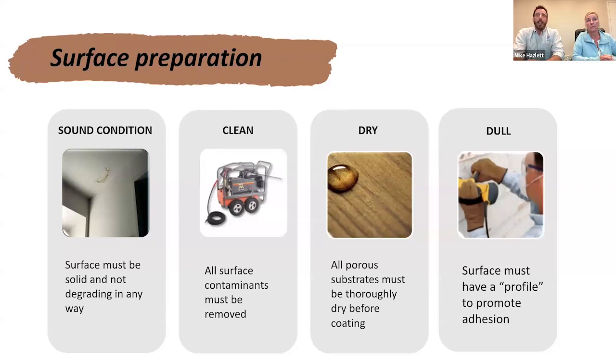Come back in two hours, maybe after lunch, and more than likely you'll have condensation underneath that bag. That shows that even though it visibly looks dry, there could still be moisture coming out of that surface. And you can apply that same theory to your stucco buildings or other areas as well. Yeah, parapet walls are a good example of that too.